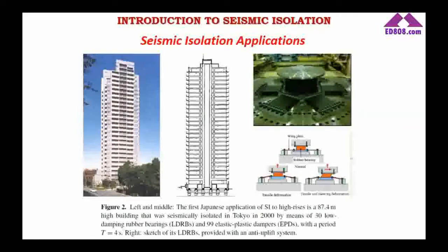And the other drawback for applying this isolation technology to high-rise buildings is that, since these are slender buildings, there can be some uplift or high tension forces on the isolators. We do not want these. The isolators can get damaged with tension forces or uplift forces. Mostly the codes restrict this. But in Japan, they somehow solve this problem with different kinds of solutions.